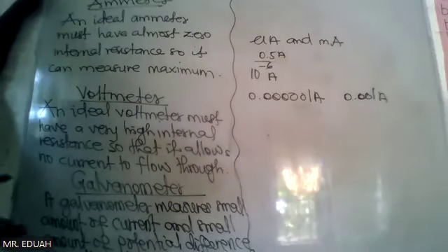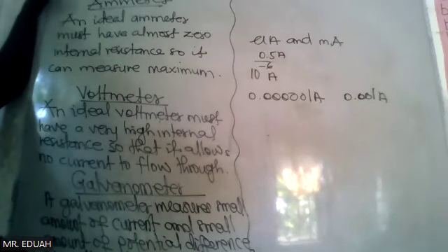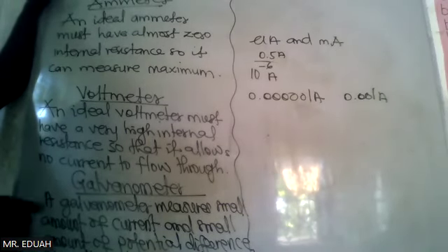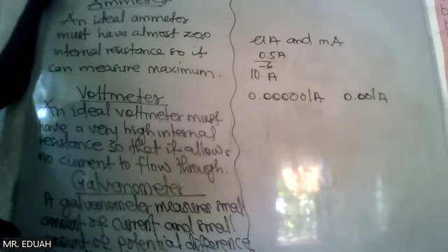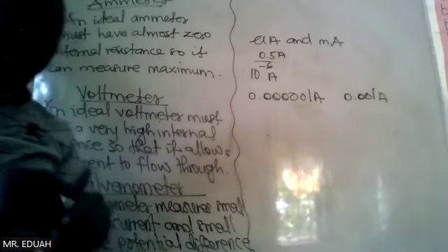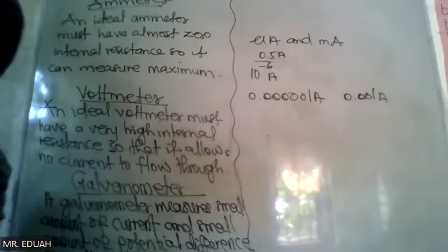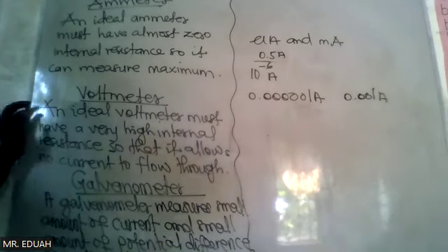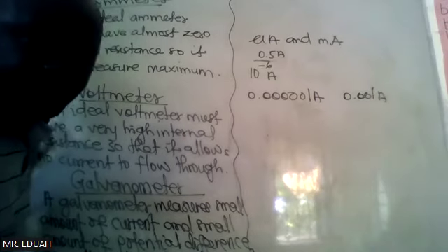And that's the calibration of galvanometers. If it's for measuring current, micro and milli. If it's for voltage drop, micro and then milli, very, very small. The reason for which is it is for measuring small amounts of current and small amounts of potential difference between 2 points. Please, is it well understood?